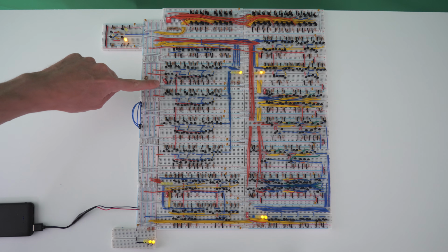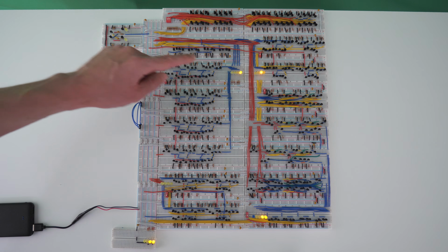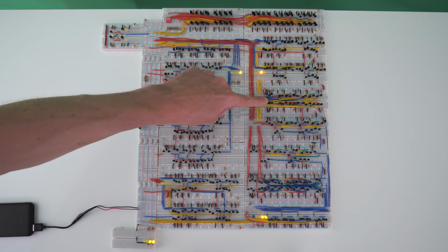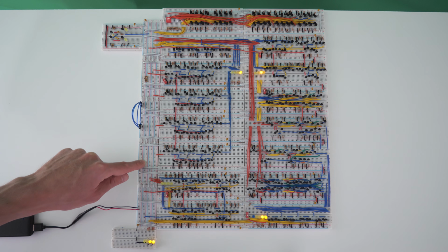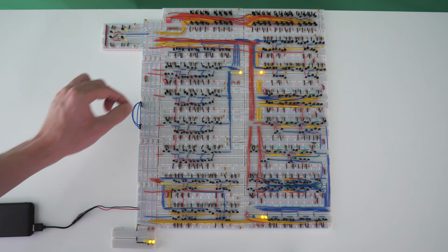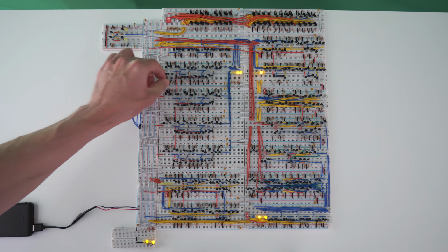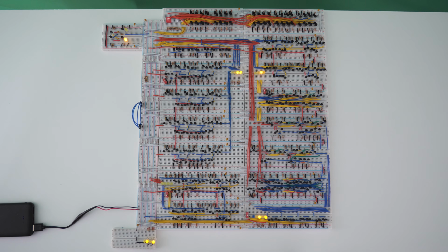But we actually have to flip this switch pretty quickly because the A register is actually connected directly to the ALU, so it will update this value and then send it back to the data bus. So we can actually only have this be on for 1 clock pulse. So I will flip this back and forth very quickly, and now you can see that we have 3 in the A register, which is what we want.